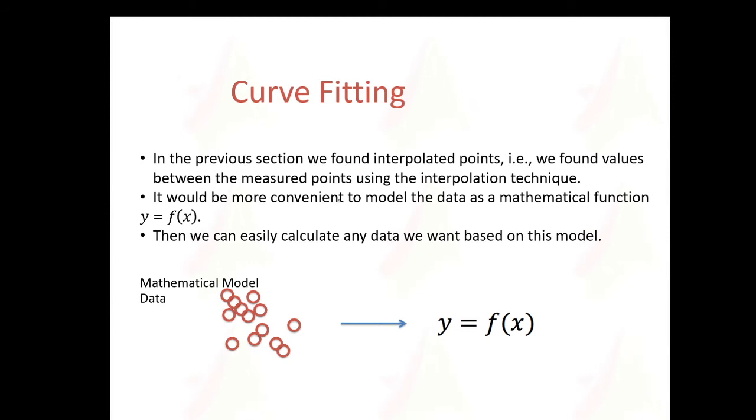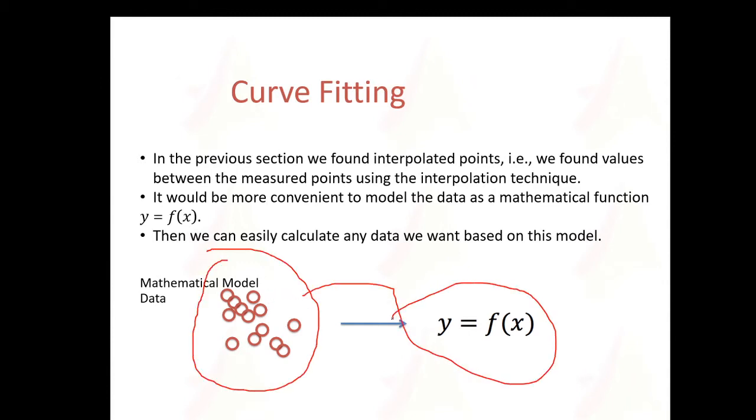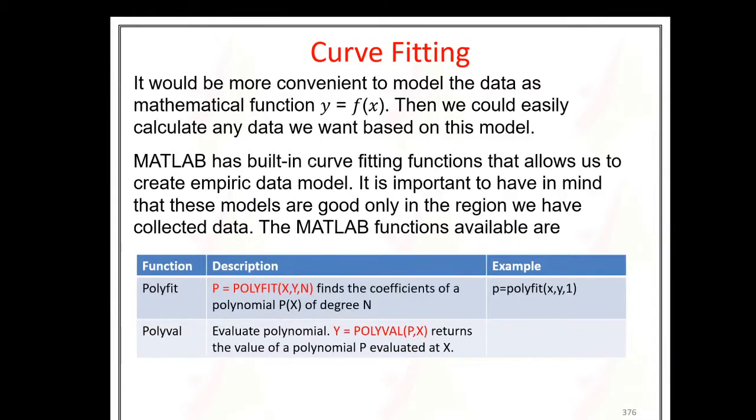So this is the input data. From this I am going to model it as y equal to f of x. You can see the functions polyfit and polyval are available. Matlab has built-in curve fitting functions that allow us to create an empirical data model from the given data. It is important to keep in mind that these models are good only in the region where we have collected data. What I am trying to tell is that within the range of the collected input data, it gives good outputs.